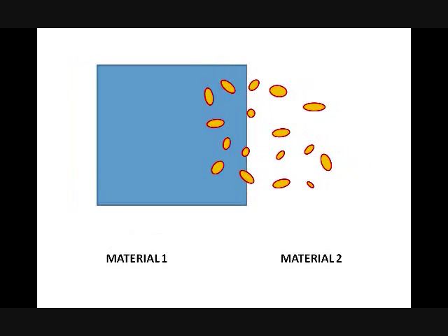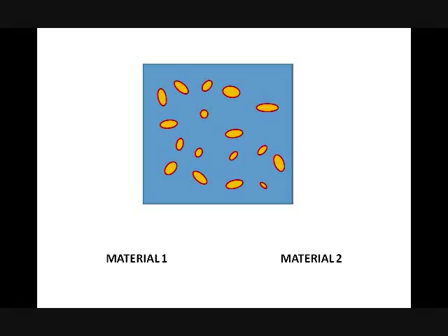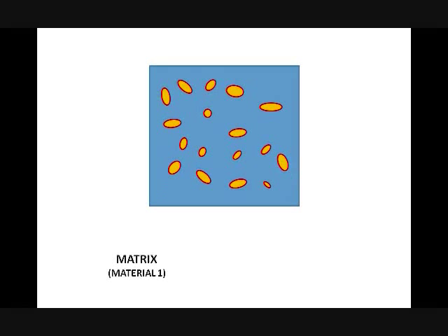Composite materials are made from two or more constituent materials or phases which have different properties. For example, cement, which is used for making concrete, shows very good properties in compression while not-so-good properties in tension. Constituent materials or phases are divided into two groups, matrix and reinforcement. So in a composite material, at least one portion of each is required.